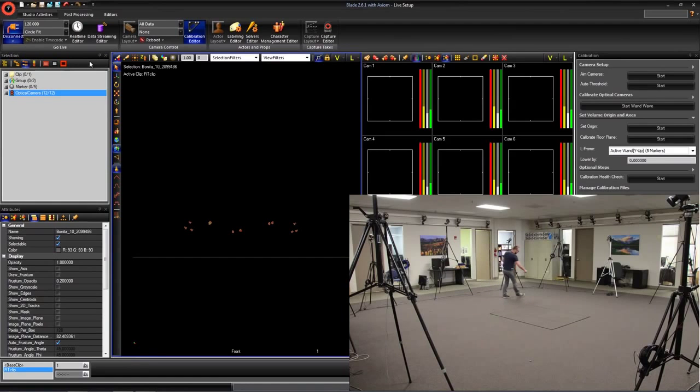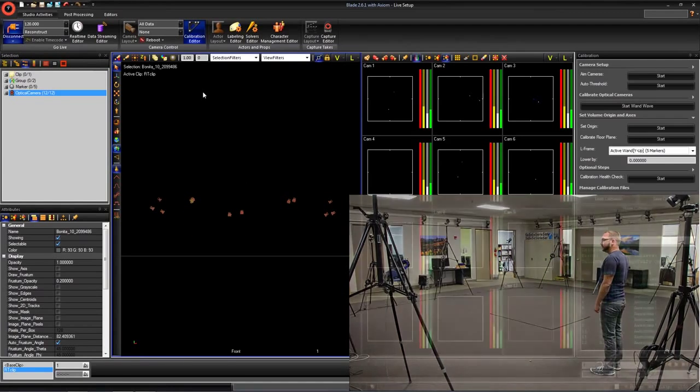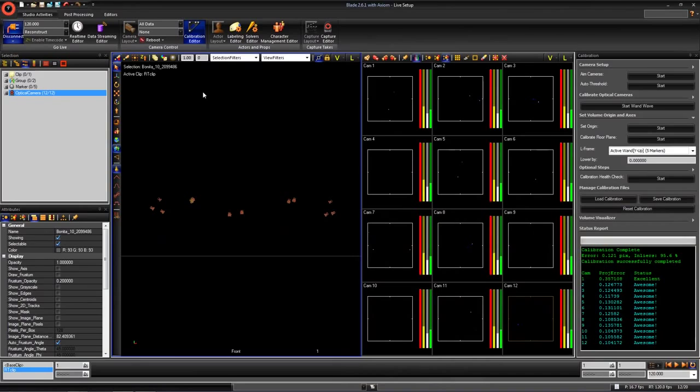I can change this by going to the top left up to the drop box that says Circle Fit. When I click that, I get some more options. I want to tell the system to reconstruct the markers in real time. This is going to allow us to see the markers in the 3D perspective view. After I turn that on, I can adjust the display size of the markers in this text box at the top of the 3D perspective window.